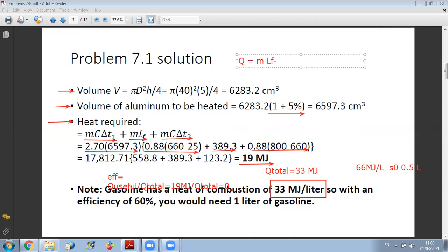So here you are heating your system. Then the energy absorbed by the solid state will be transformed. This energy will allow molecules to get far from each other and to go from solid to liquid state. So whenever you complete your fusion process, you go from 100% solid to 100% liquid. The amount of heat provided should be equal to the latent heat of fusion, which is provided in joule per unit mass, times the mass which you are heating, which is in gram. By doing this product, you get the amount of heat in joule required to change phase from 100% solid to 100% liquid.